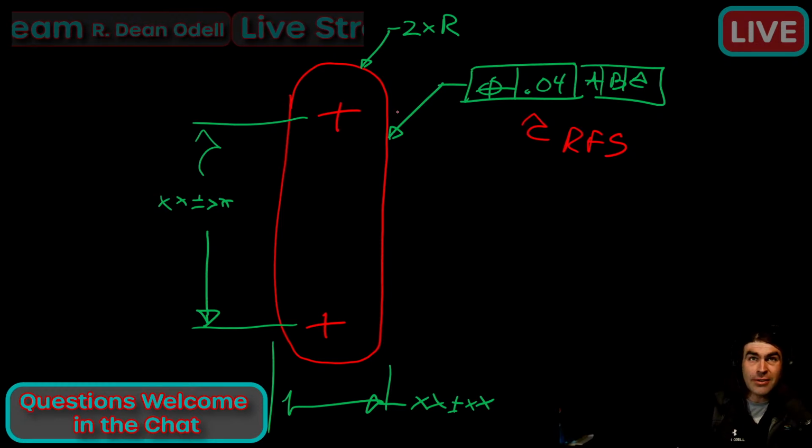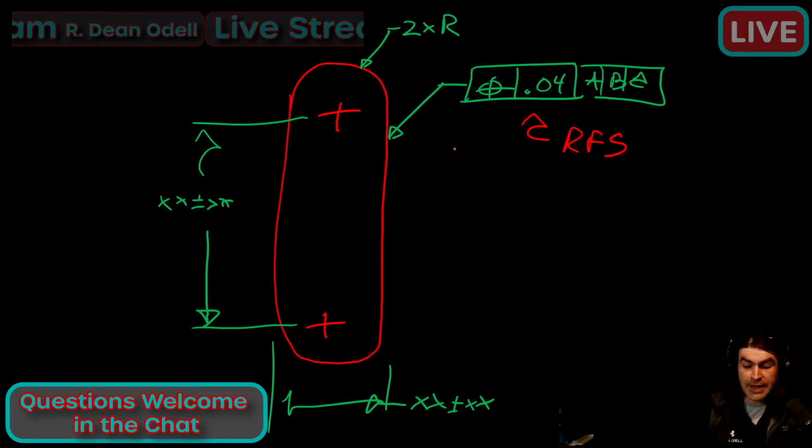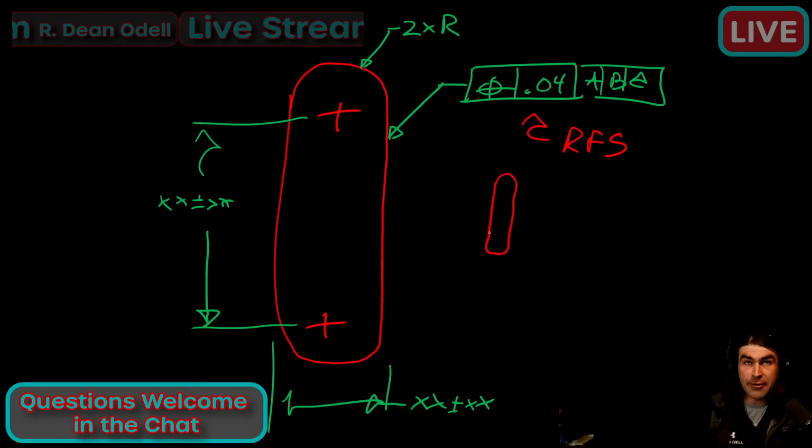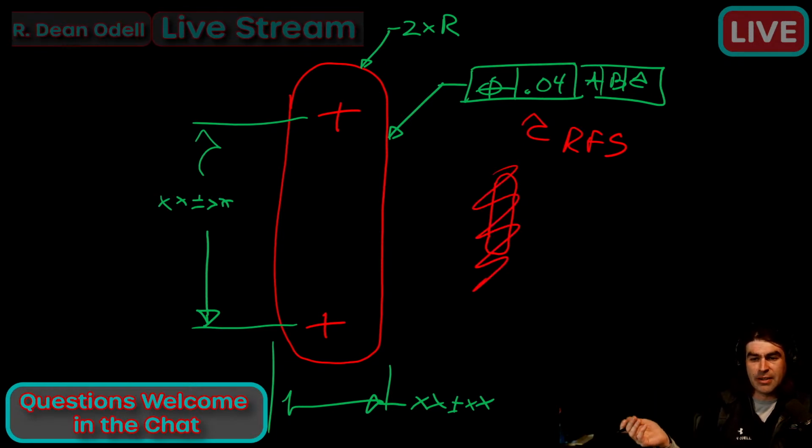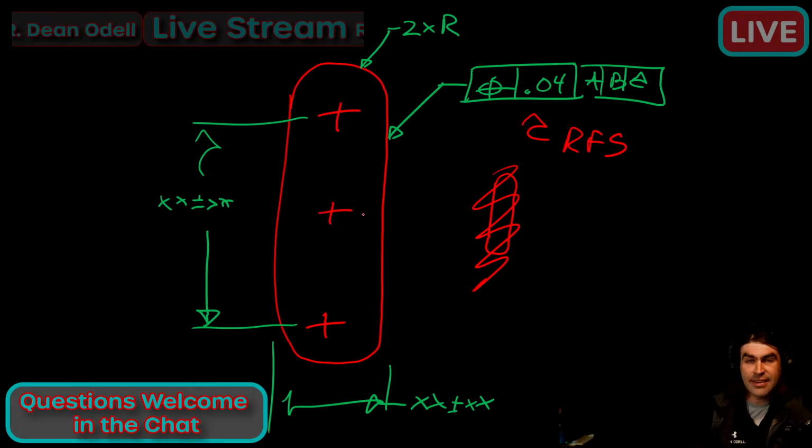With this, the question is, what is the feature and what is the tolerance zone? I can tell you right now, there's no support in Y14.5 for a small slot-shaped tolerance zone. That's not a thing. And the other thing is, what's the derived element here? Is it an axis in the middle of the slot? And if so, where does it come from?